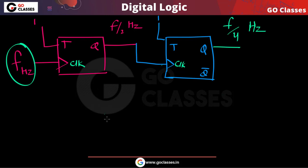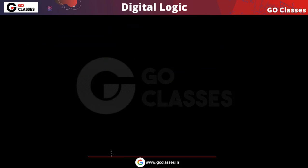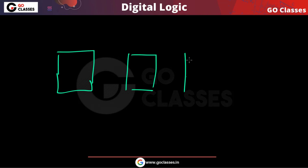Now you can notice, if you want to divide the frequency by 2 power k, then in the same manner, in this similar manner, you can connect k flip-flops. For example, this is your T flip-flop, this is another T flip-flop, this is another T flip-flop, this is another T flip-flop.